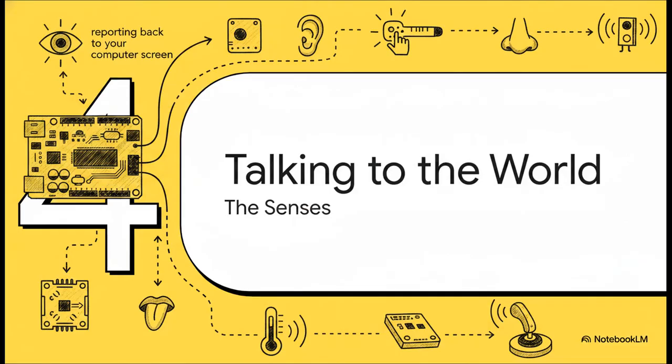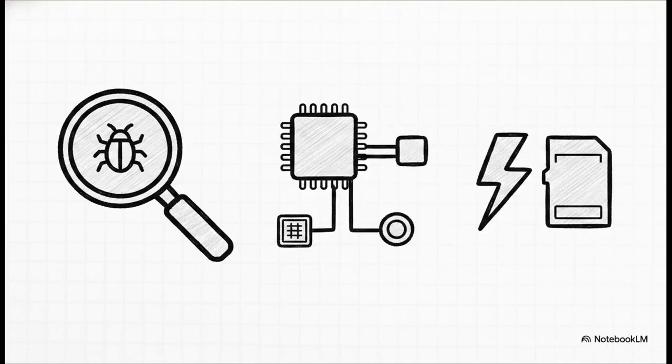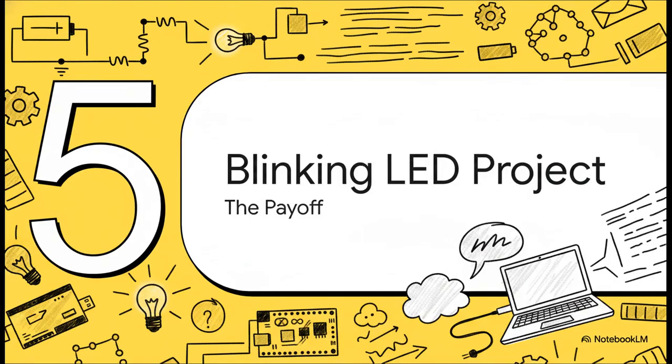Section 4. Talking to the world. The senses. So the crucial point is that different hardware needs different ways to chat. Serial, or UART, is going to be your daily driver. It's absolutely perfect for printing text back to your serial monitor so you can debug your code. Then you have I2C, which is this brilliant protocol that uses just 2 wires to daisy-chain dozens of sensors together. And finally, for the really heavy lifting, like SD cards or Wi-Fi modules, SPI gives you that high-speed data transfer you need.